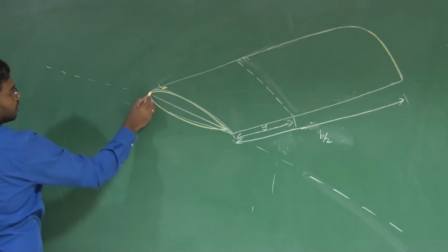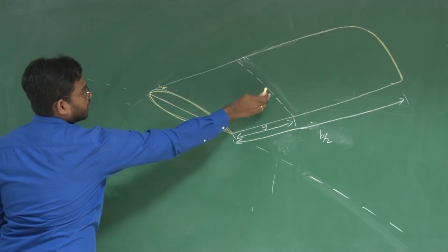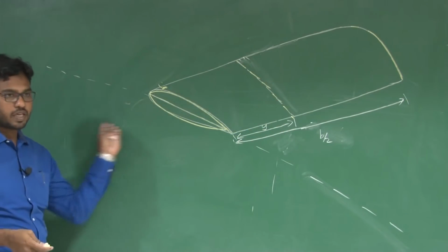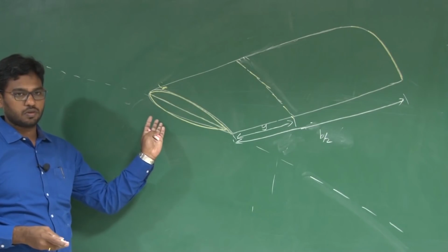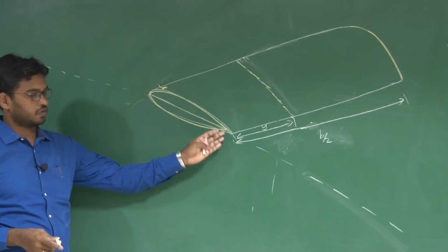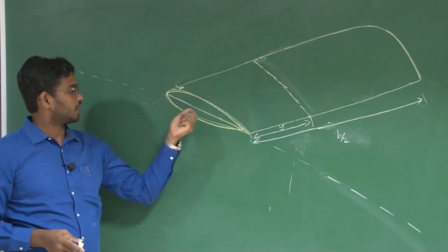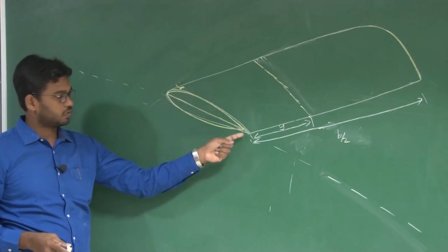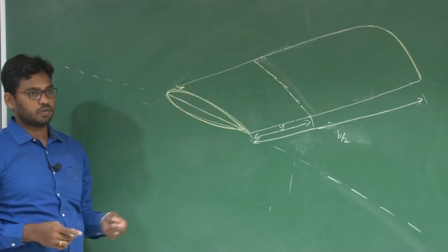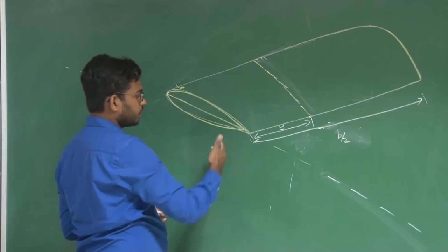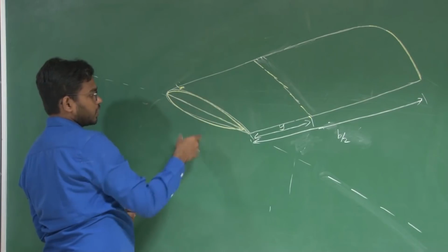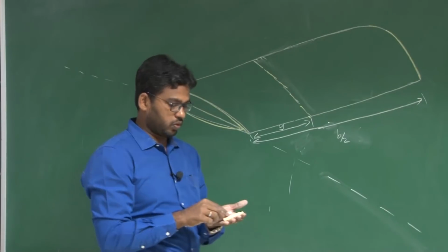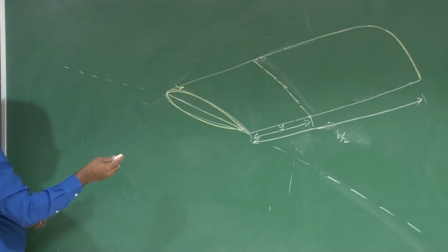So although the chord line of the aerofoil at this location is in the same plane as the chord line of the root chord, the profile changes because I am changing the aerofoil, and the corresponding upper and lower coordinates are different compared to the aerofoil used at the root. Because of this, although there is no physical rotation given, the wing looks twisted. You call it aerodynamic twist.